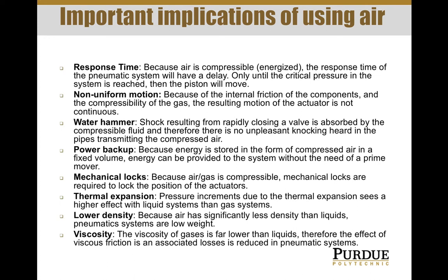There is also an issue with non-uniform motion for the same reason. Because there is that compressibility, the air will compress until it can break the friction of the system, and then it will start moving. So till then, you're just compressing the air, not moving anything. So those are potential disadvantages of compressed air systems.